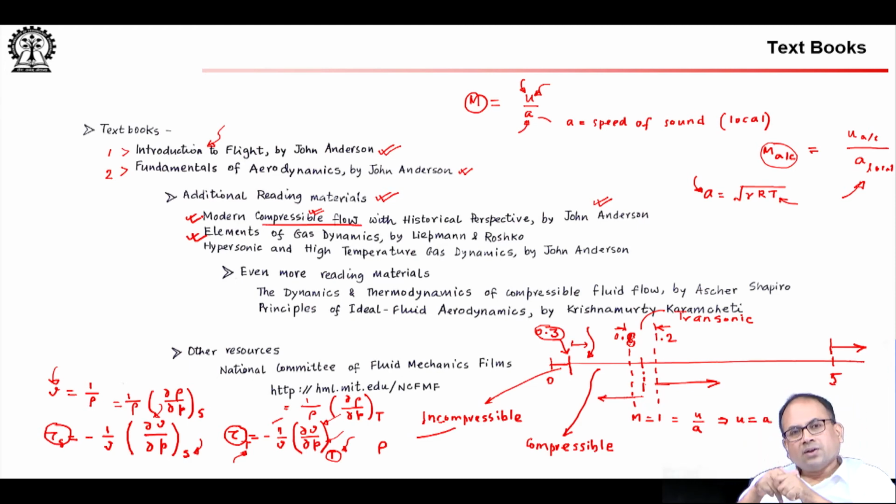In fact, there is often this question that is asked, what is a wing? You see the wing on an aircraft. So, if someone asks you the question, what is a wing? You might tend to answer that these are the two structures on both sides of an aircraft, but technically any object, any body which when properly oriented with oncoming stream of air produces lift that is considerably greater than drag can be considered a wing. Okay. So, that is from Karamcheti. So, Karamcheti's book gives you all these nice insights into these kind of things.